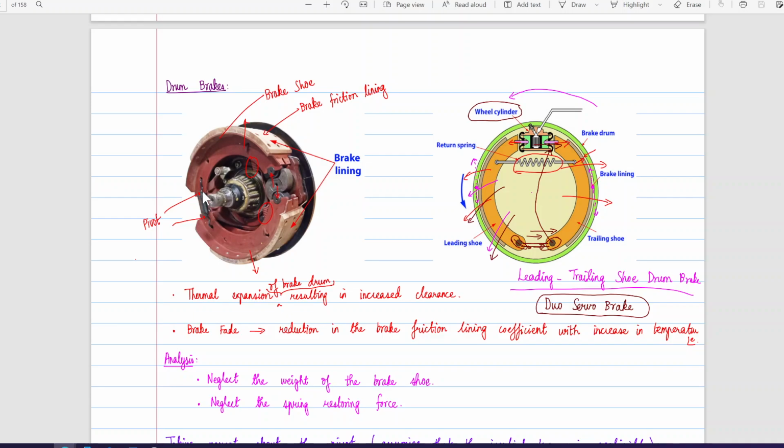Okay, so mounting of these brake shoes has the following things. There is one spring here and another spring here. These are the springs which keep the brake shoe at its position so that it does not randomly go and rub against the drum. Okay. Then there is this cam called S cam. If you rotate this S cam, it generates the force which pushes at these two pins. Okay.